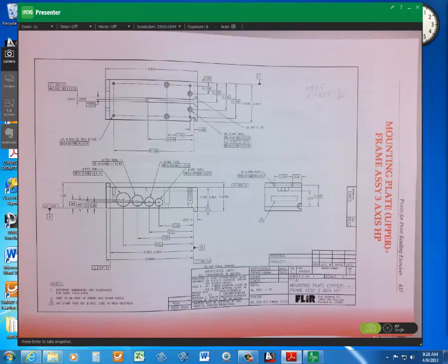On one end it's 0.312, the other end is 0.316, and maybe a half thousandth or something. If 312 fits, flip it over, stick the other end in, and it doesn't fit, okay, so we're good. You've checked it for its full range of sizes without using a measuring tool.